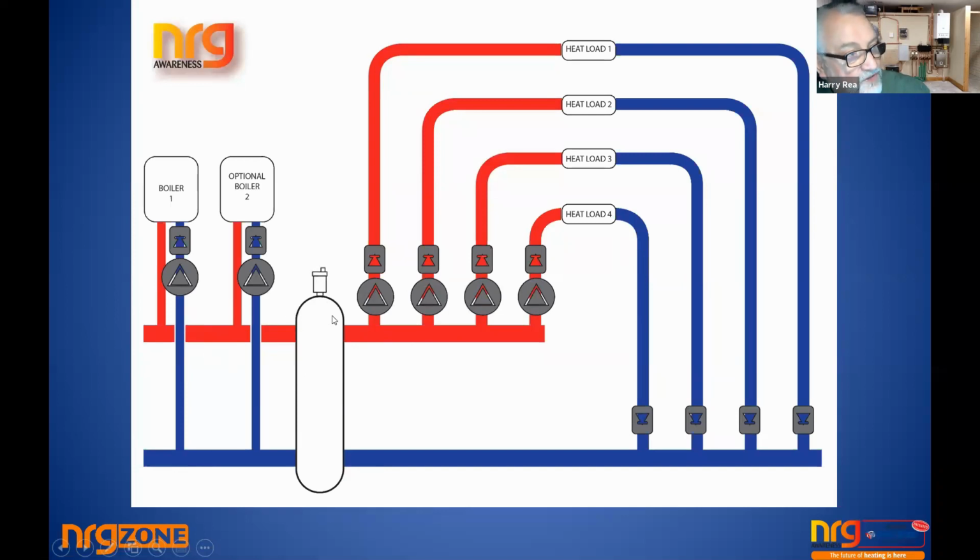And again, if the header is sized properly, you're going to find that even on a standard small system, the header is about the equivalent of 2.5-inch iron pipe. When I say standard, that would be up to, like, let's say 50 kilowatt, 70 kilowatt or something like that, maybe say 50 kilowatt. Anything more than that, the header has to go much, much larger. So if you're 100 kilowatt, your header might need to be a 4-inch diameter pipe.